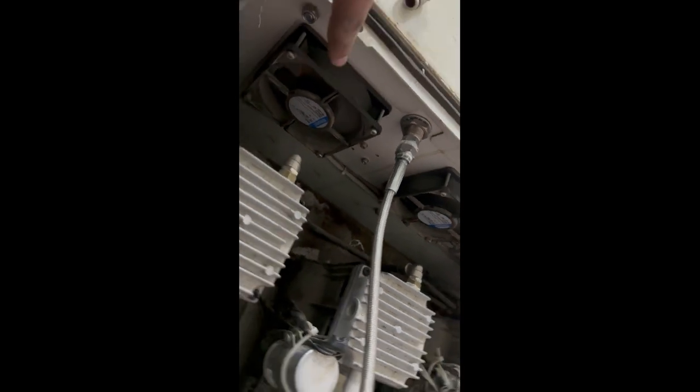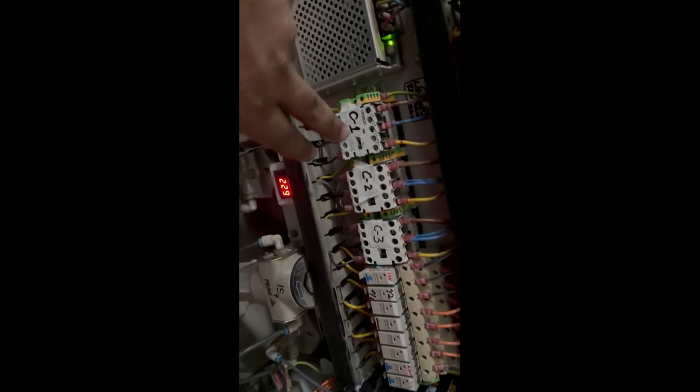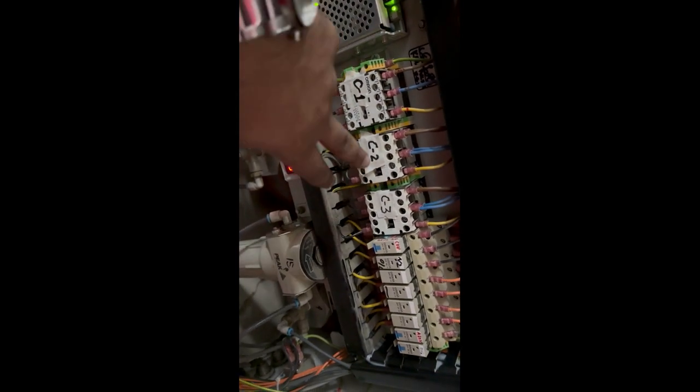These things, and this is not the only coil. Here we have another coil inside this cabinet. The coil from this line goes to this line. So there's the inlet line and outlet, and here we also have some more. Now you can see both pressures have been reached here, and that's why the compressor has switched off. So it's normal operation. Here we have 3 magnetic contactors for compressor 1, compressor 2, and compressor 3.